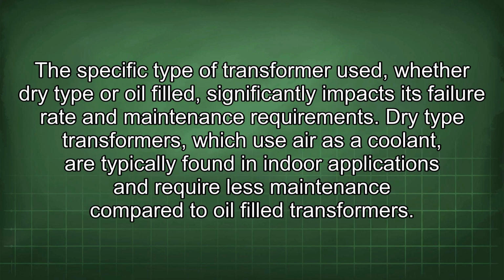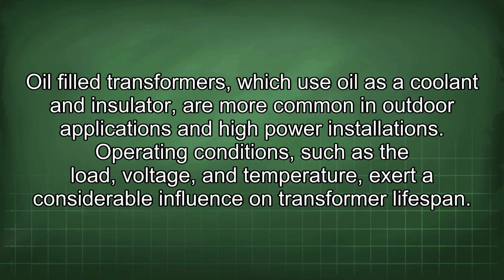The specific type of transformer used, whether dry type or oil-filled, significantly impacts its failure rate and maintenance requirements. Dry type transformers, which use air as a coolant, are typically found in indoor applications and require less maintenance compared to oil-filled transformers. Oil-filled transformers, which use oil as a coolant and insulator, are more common in outdoor applications and high-power installations. Operating conditions such as the load, voltage, and temperature exert a considerable influence on transformer lifespan.